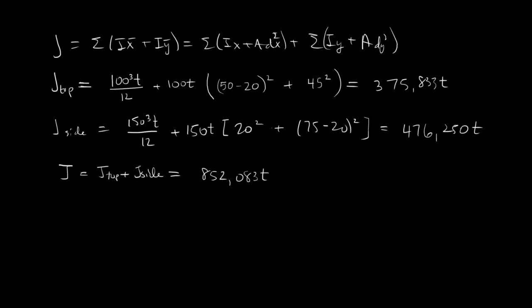And when we evaluate that torque on the bracket at this location for the x bar and y bar, we have 20 kilonewtons, and we have a torque. This load was applied at a distance of 280 millimeters, which makes this torque 20 kilonewtons times 280 millimeters, which is 5,600 Newton meters.